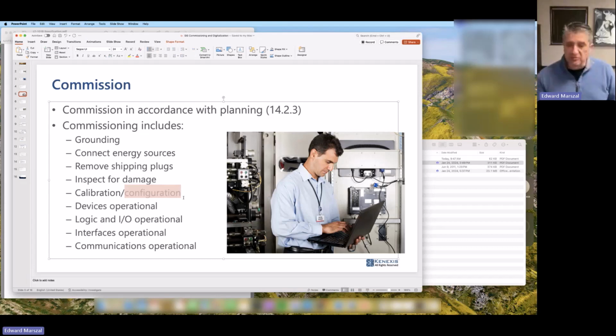And I say that this is the most common thing that I punch out because this is what happens when I'm doing a functional safety assessment or an audit on commissioning. I ask, okay, so for this device, did you check the configuration of the failure mode? And they're like, I'm not sure what you're talking about. And I say, okay, well, if this device self-detects that a failure has occurred, what output will the transmitter give you? And the answer almost universally is, okay, well, we're using vendor XYZ. Do you know what happens by default? Yes. So most people still have whatever the default setting was when it was installed in the field. So that's something that you're going to want to check.